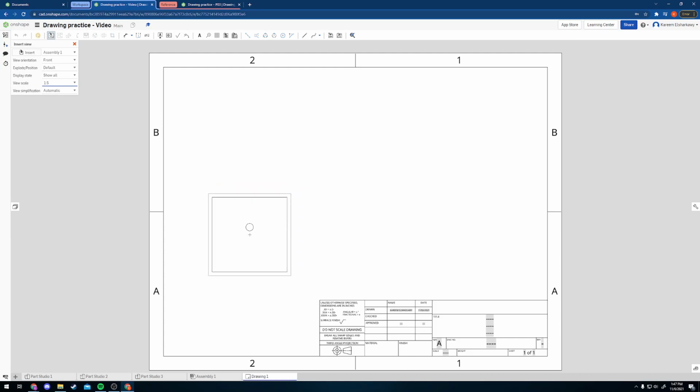Now I want you guys to click on your build space and drop your picture. This doesn't look like it conveys much information, but that's where we're going to fix that now. We need to show multiple different views of this part. Now in Onshape it'll automatically select the project tool for you, which will then move the camera in relation to your reference image. I'll show you what I mean.